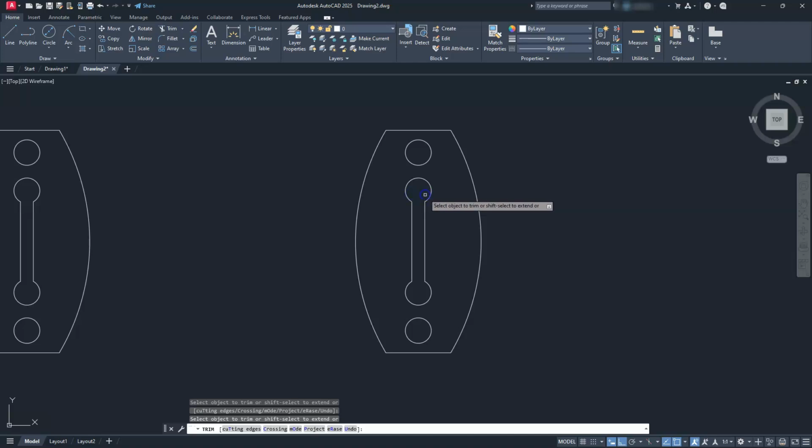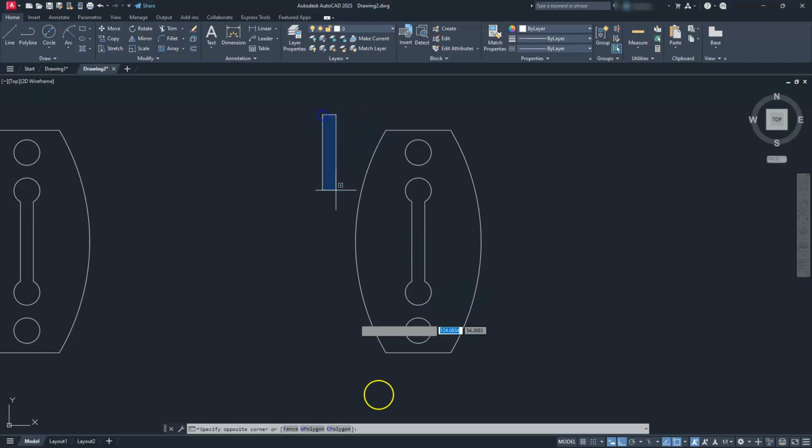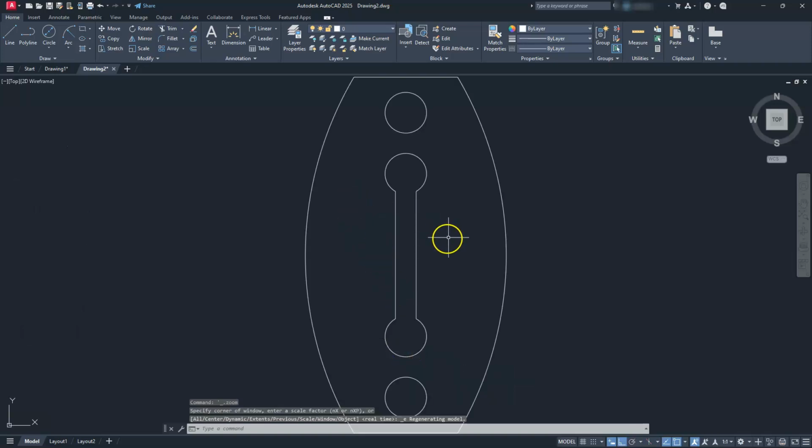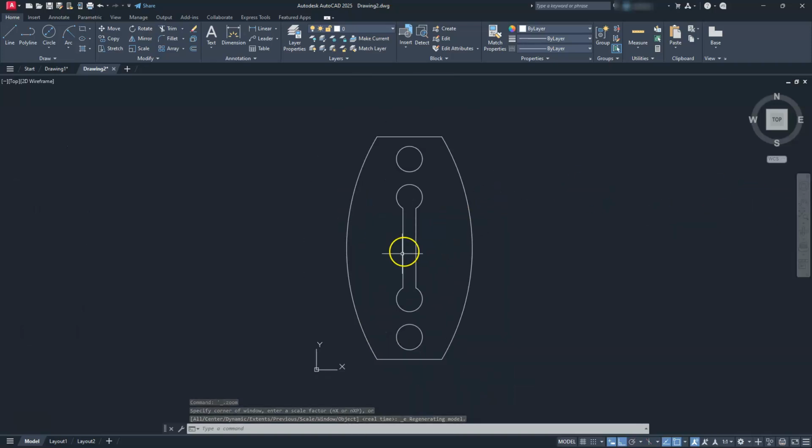Okay, so all of these are exactly the same, super easy to draw, just a matter of how you want to think about it. Now the drafting portion should be super simple for us, right? We're going to create a title block so we can get whatever the scale factor is. Let's go ahead and get rid of this one here. I'm just going to double click my middle mouse button, or you can hit the zoom extents, and that'll bring this one back. Let's go ahead and create, we don't use an A size, and in this case I'm going to use it as a portrait. So I'm going to make this thing 8.5 by 11.